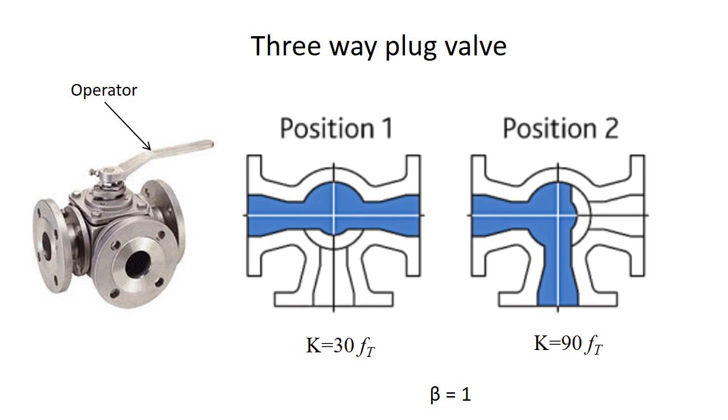One common way to change the flow direction is to use a three-way valve. Here is a simple three-way two-port plug valve. Derived from a basic plug valve, there are flow channels inside the disc, and by rotating the disc to different positions, the flow can be redirected as shown in the graph.